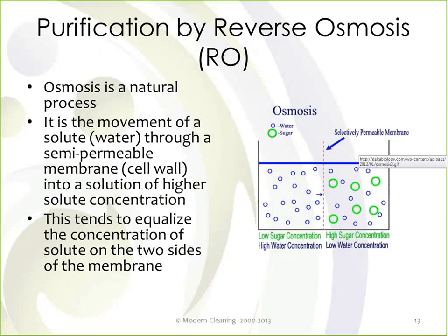This is a discussion of the reverse osmosis purification. In order to understand reverse osmosis, unfortunately, you have to understand osmosis first, so bear with me. But we're all sitting here osmosing right as we speak. It's just a matter of moving water through a semi-permeable membrane from an area of higher solute concentration to lower concentration. The image on the right shows the right side of the container has sugar water in it.